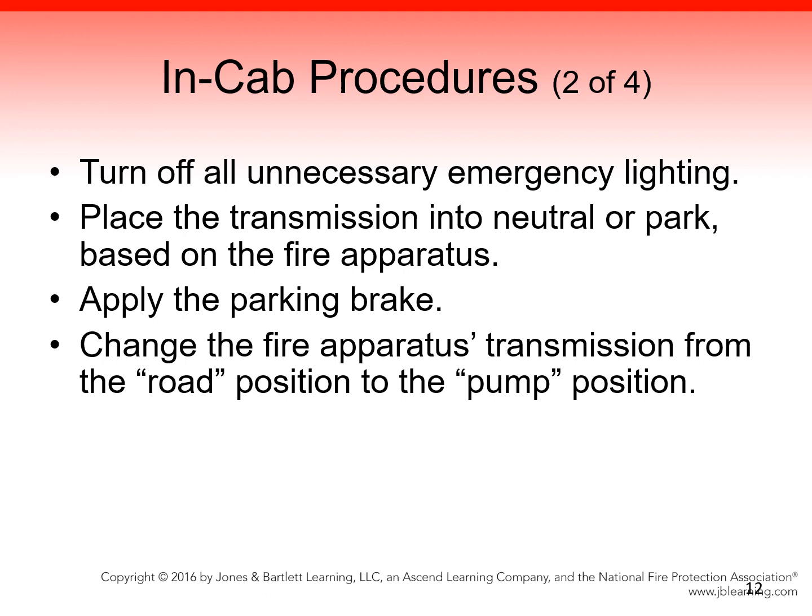When you are content with the placement of the fire apparatus, place the transmission into neutral or park based on the fire apparatus. Next, apply the parking brake. Failure to apply the parking brake on today's modern fire apparatus can cause an unsafe situation and prevent the pump's throttle from working, thus rendering the pump inoperable. Change the fire apparatus transmission from road position to the pump position. This will transfer the motor's power from the drivetrain to the pump, which allows the pump to operate.